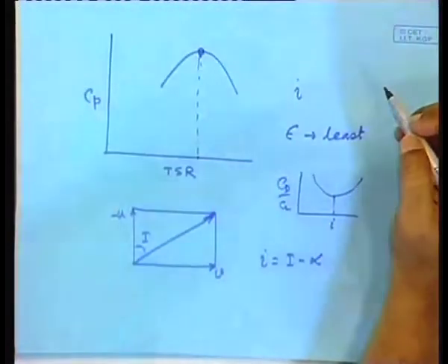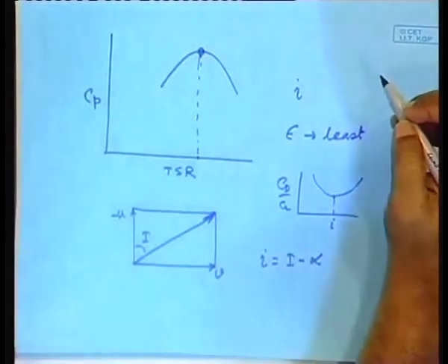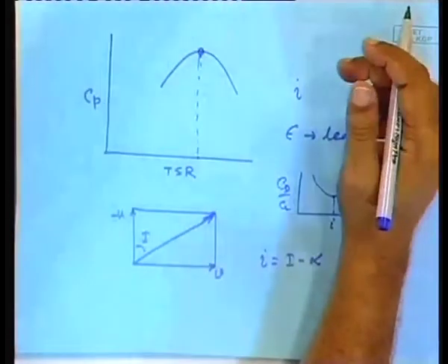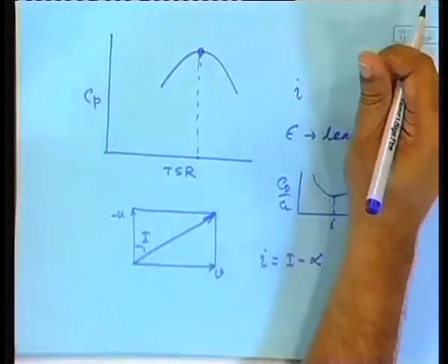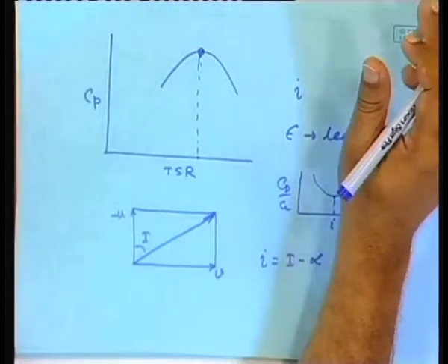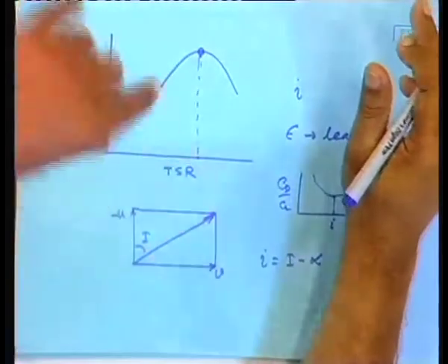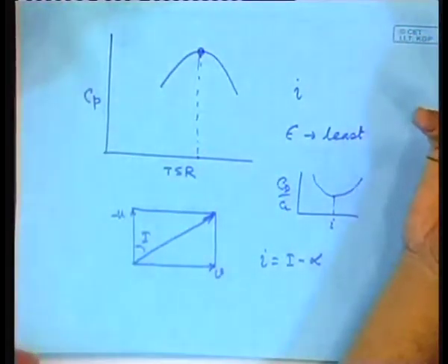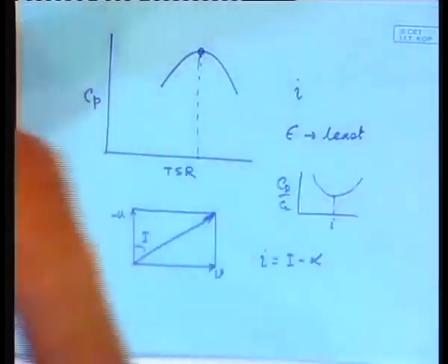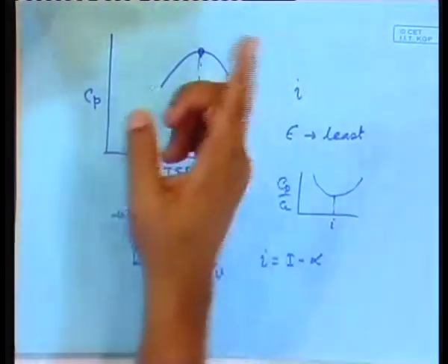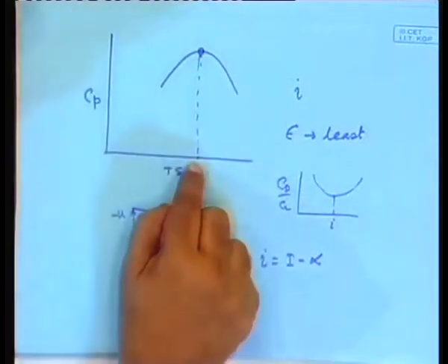And as the wind speed varies, that can be sensed, there is no difficulty about it. If it is a wind farm, there can be a single central station at which the wind speed is measured continuously. So, you have a sense of the wind speed. The rotational speed can also be obtained very easily, because the turbine is rotating, you can always sense what is the speed. So, all the time in real time you can measure the TSR, right.